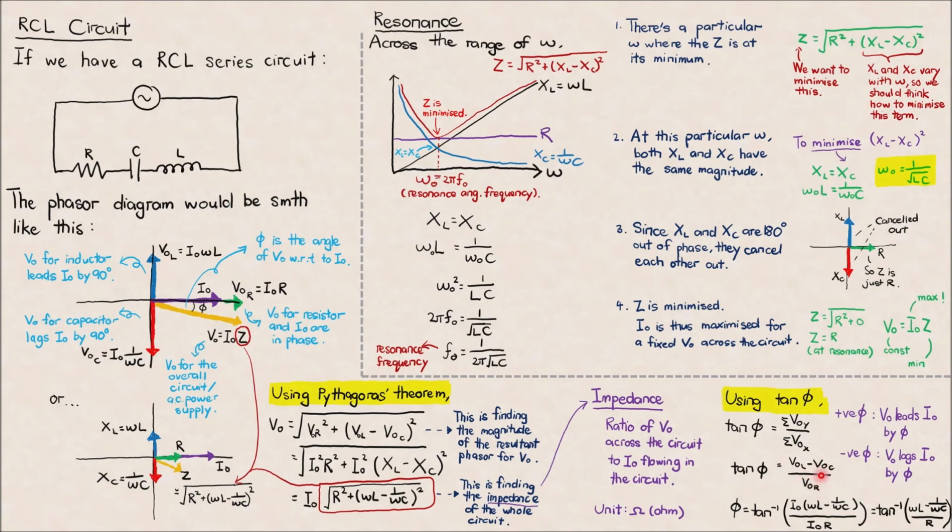We are talking about phasors here, but I keep talking about them like vectors, but they are not actually vectors. They are rotating vectors, and the rotating vectors are just to show you the phase relationship. The process of doing the calculation is similar to handling vectors, but these values are actually scalar values. I know it's a bit confusing, but you just need to know that it operates like vectors, but it's not exactly a vector. The vector is just to show you the phase relationship.